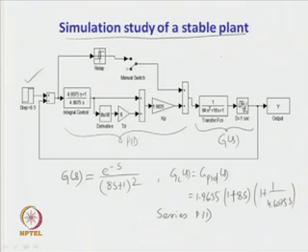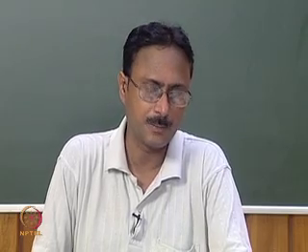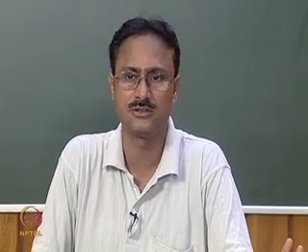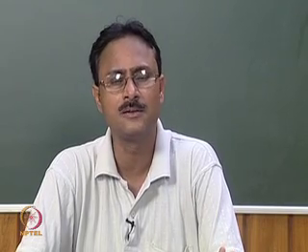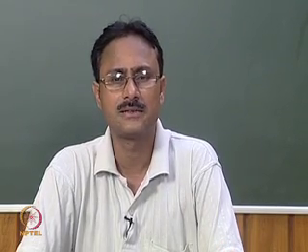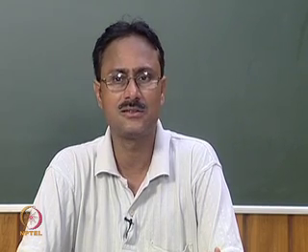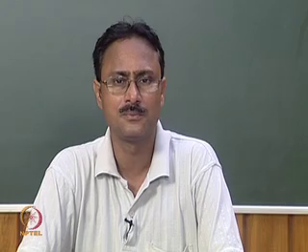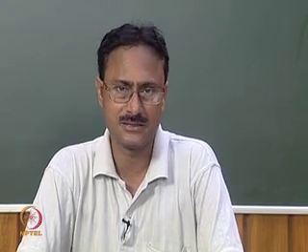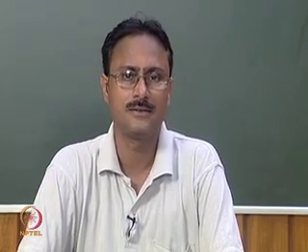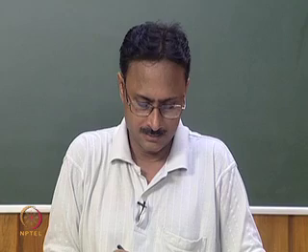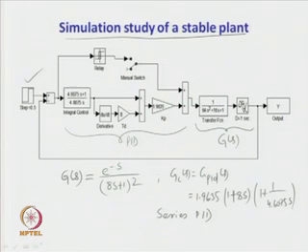After obtaining the limit cycle output for about 3 stable periods of output, the relay is switched off, because after that we need to make the measurements, and after making the measurements we get the dynamic model of the process, and based on the dynamic model parameters of the process, the controller parameters are updated. That is how identification and tuning is done online. Let us see the simulation result we get from this scheme.